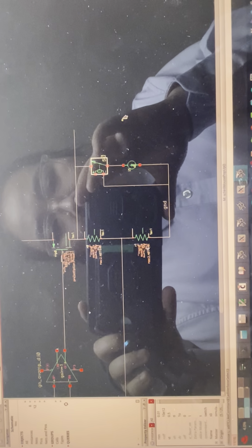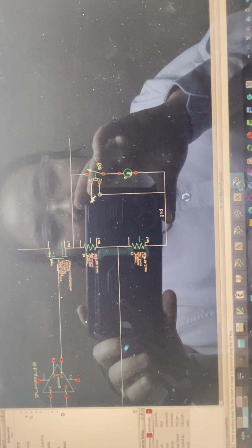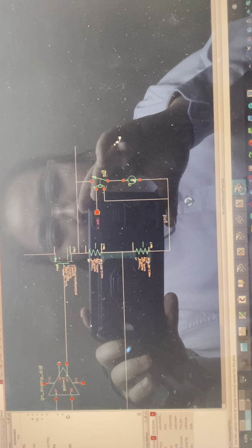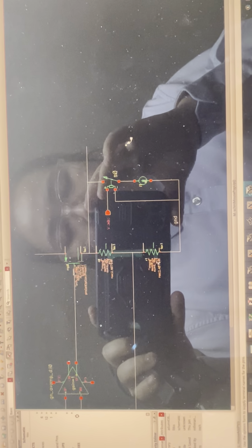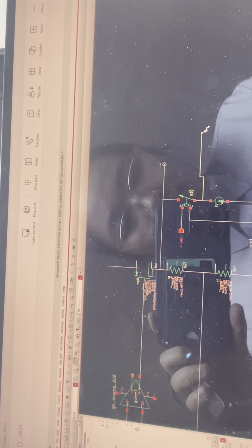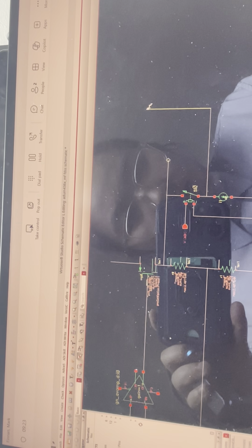So you can create another node here, a pin or a V load or something, and you can drive that with an actual voltage source. But because switches are funny, you probably want to do something like this as well.